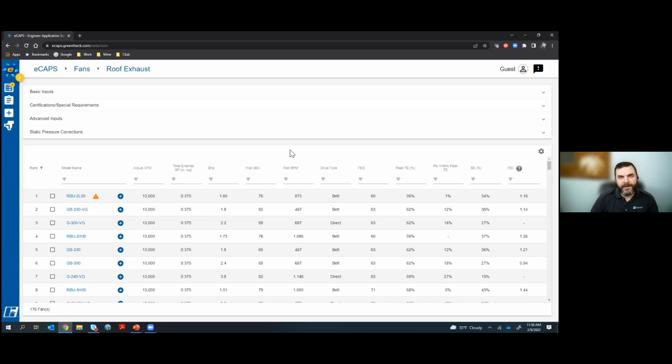Certain areas, and I've seen it in Oregon, have a lot of their fan schedules and specs actually state a minimum FEI. Here in Wisconsin, I haven't seen that yet. Honestly, most of the engineers around me haven't even played with FEIs yet. It's not a requirement, and they're not going to do anything with it. But you should be aware of what's coming for requirements and the benefit that this value can hold for you. So that's my way of skirting around a better answer.